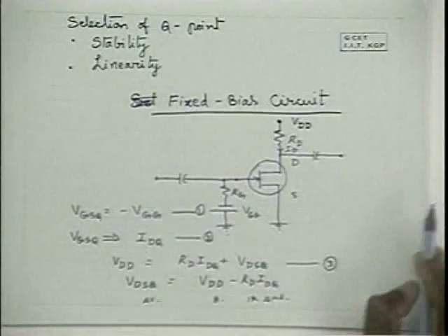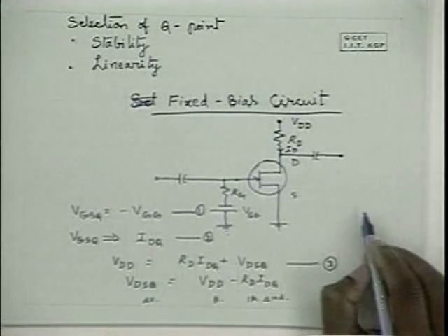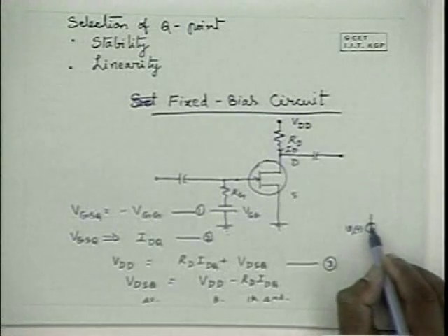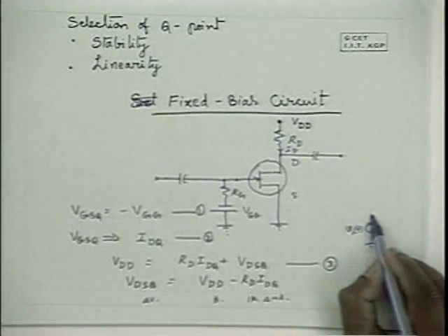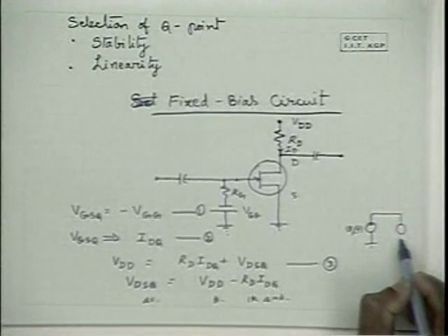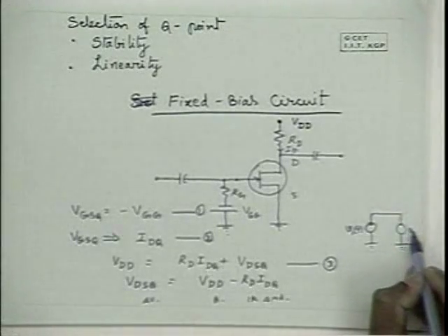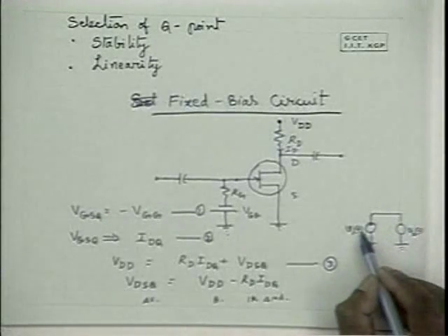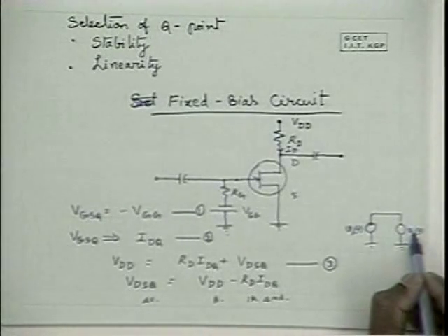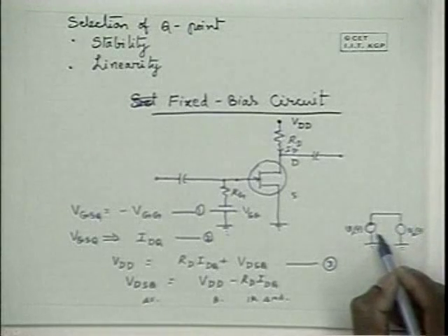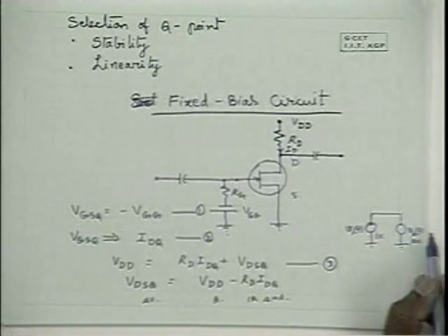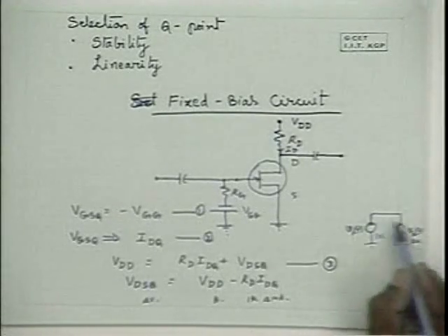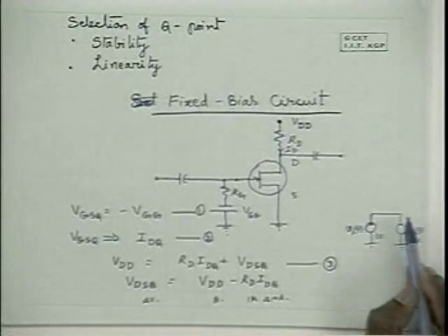If you apply two different voltage sources, say V1(t), a time function, a signal source, and another signal source V2(t), and if you connect them together, it is just short circuiting one voltage source to the other. If this is, say, 1 volt fixed and this is 2 volts fixed, this is getting short circuited by this. So 1 volt of signal, the difference between these two, is getting short circuited.